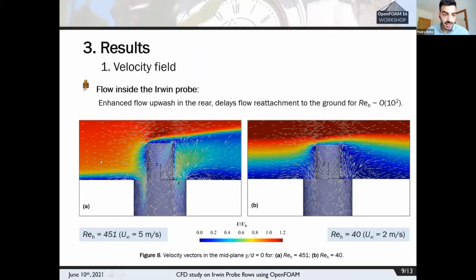So first, it is evident that besides being directed over the crest and around the sides, a part of the flow is also diverted down into the cavity, which forms a circulation inside it. We also see that in the back face, due to that circulation, there is an attached upwash that runs up to the trailing edge of the tube.